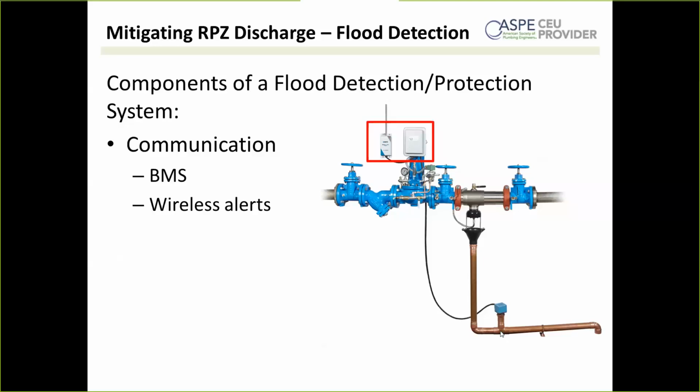I'm not exactly sure how you do it for the kind that's built into the relief valve, other than by forcing the relief valve to open. Doing something like bridging between two test cocks is really creating a cross connection itself. So I'd be very careful with that.